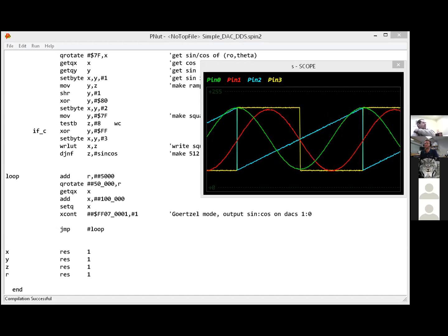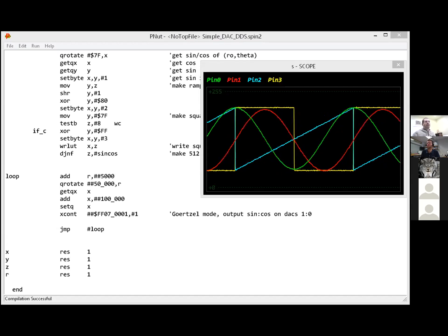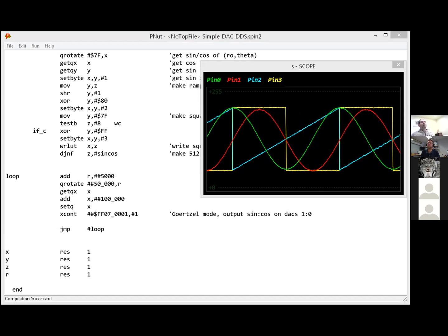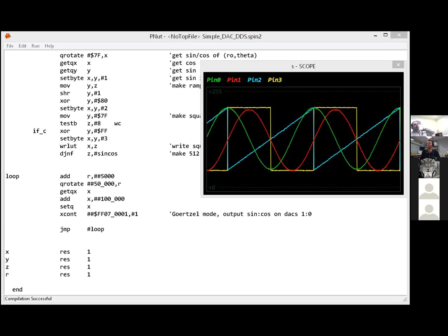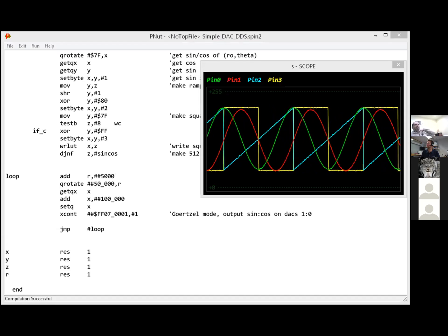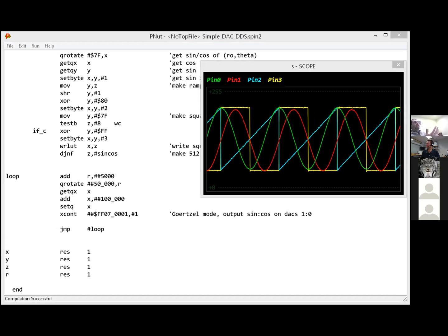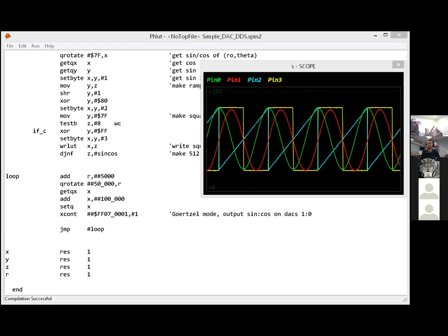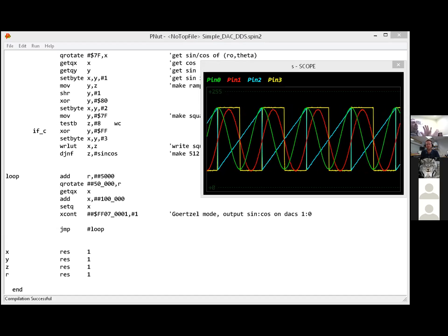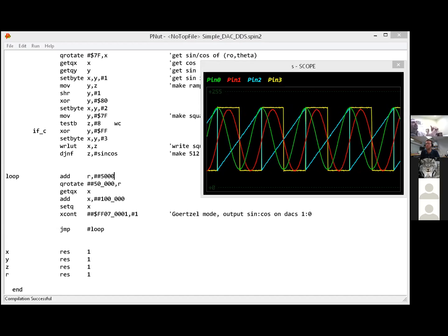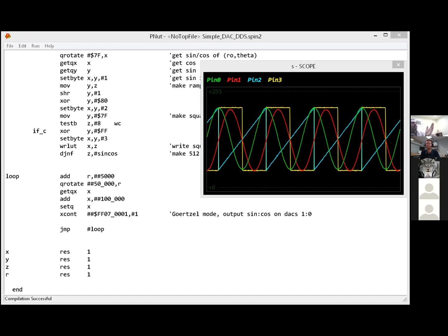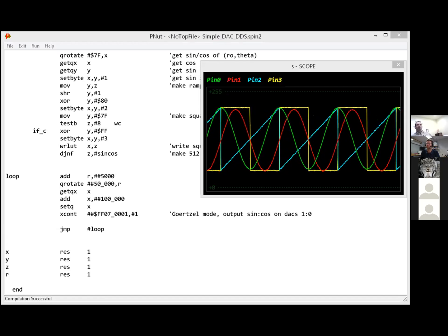And you can have the streamer just spew data that either gets from the LUT at random access points based on an NCO, or sequentially from hub memory, or I think it can even do it from IO pins coming in. You can stream all this into your DAC channels, and then each IO pin can tune to a certain cog's DAC channel. So pin 0 is going to be channel 0, but for any of the cogs. Pin 1 is going to be channel 1, but for any of the cogs. And pin 3 is going to be channel 3 for any of the cogs. You can pick which cog. And then when you get to pin 4, you're back to channel 0 again. So each cog can output 4 discrete channels.